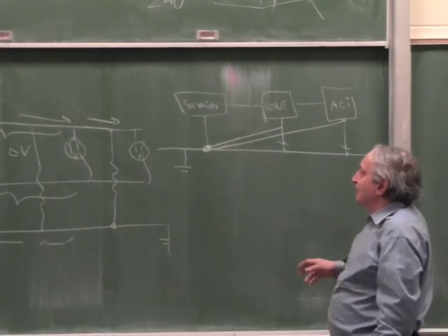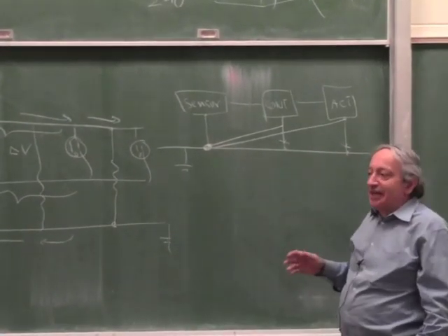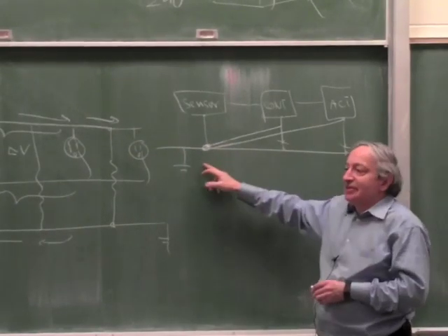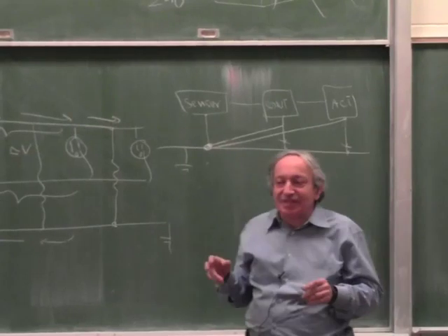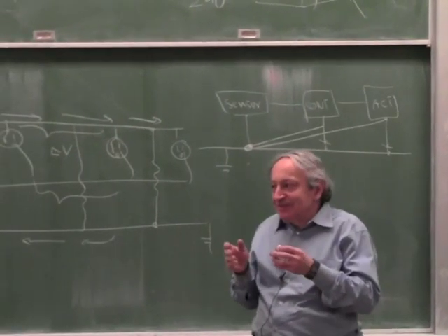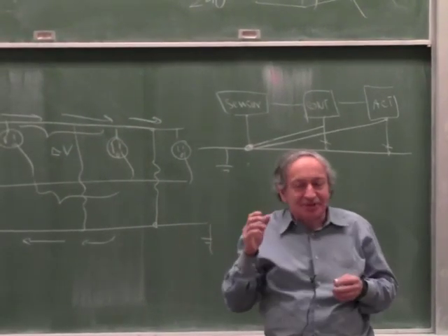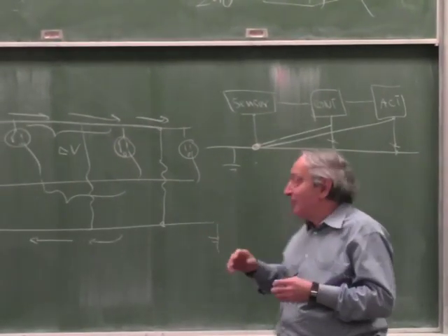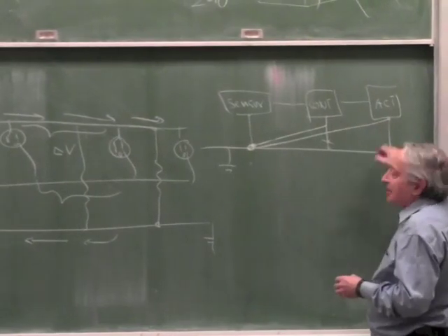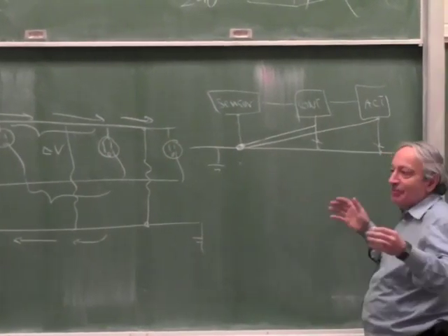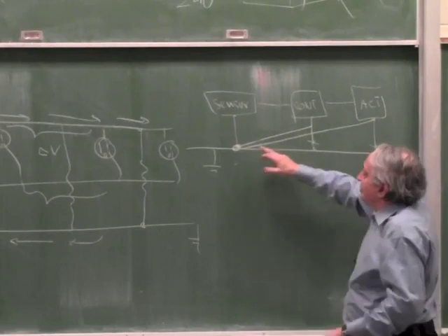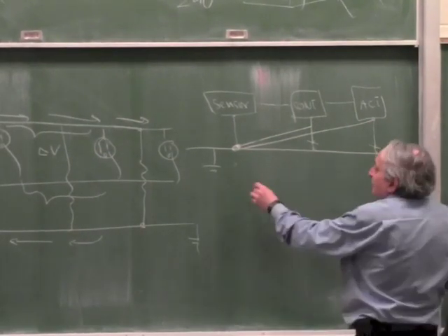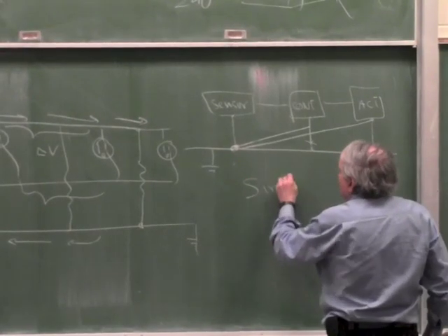Sometimes it's also referred to as audio style ground, because in audio amplifiers inside the parts are grounded this way. Because an audio system is very sensitive to picking up hum, because 60 hertz of the audio system, you can hear it. It's audible. And this can happen if, inside the audio system, you have multiple grounds. So inside, if you have a big audio amplifier, they do this. They bring everything to one point. Okay? So that's kind of single point grounding, or central point grounding.